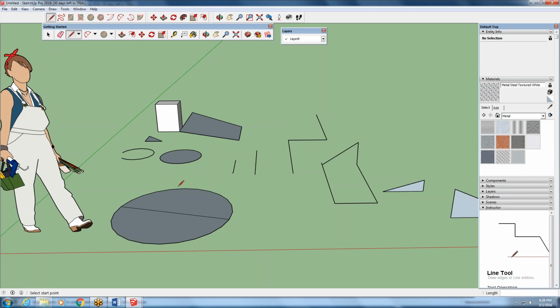There's a variety of points that you can snap to, and those are called inferences. And it's inferring where to snap to. So center is a good one. Again, midpoint, endpoint, intersection, although we don't have an example of it that we can probably get to pop up yet.